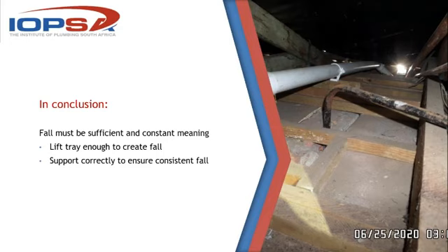So that's my point that I wanted to get across today, is the imperative thing is the fall. Yes, there's good practice about minimum changes of direction, only 45-degree bends, but as you can clearly see, 90-degree bends don't. It's not to say that it's a failure. It works because I'm complying to the standards. I'm saying that the standards require me to discharge at 40 liters a minute, and I am doing so. But I'm doing so through proper design and fall.